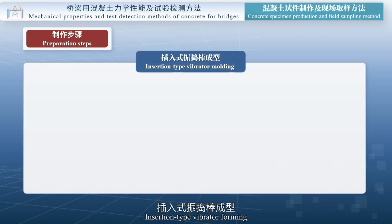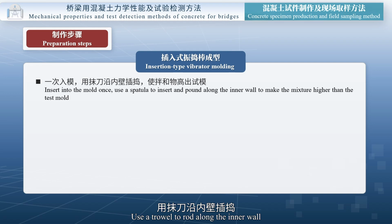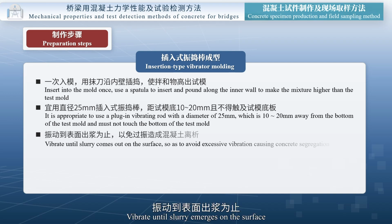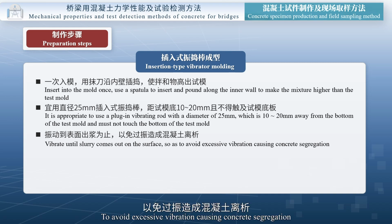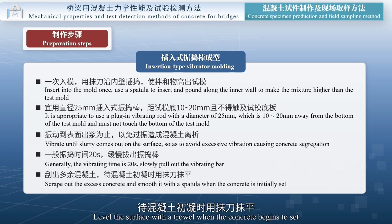Step 4. Insertion type vibrator forming. Fill the mold in one go. Use a trowel to rod along the inner wall, making the mixture higher than the test mold. It is advisable to use a vibrating rod with a diameter of 25 mm. Insert the vibrating rod 10-20 mm from the mold bottom, and it must not touch the test mold base plate. Vibrate until slurry emerges on the surface, to avoid excessive vibration causing concrete segregation. General vibration time is 20 seconds. Slowly withdraw the vibrating rod. Scrape off excess concrete. Level the surface with a trowel when the concrete begins to set.